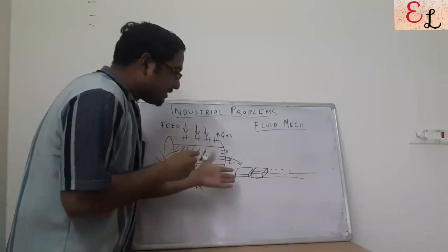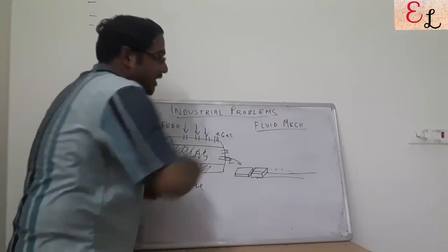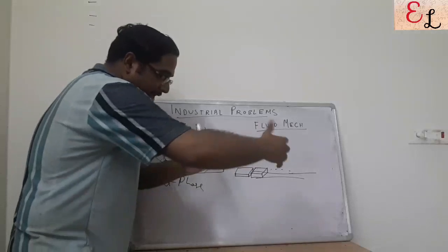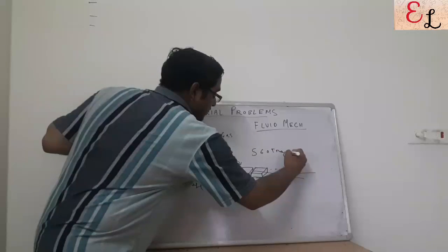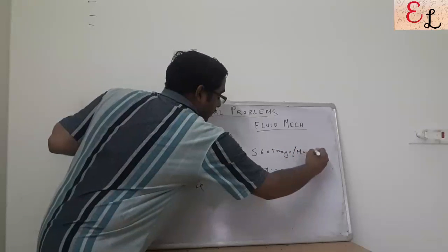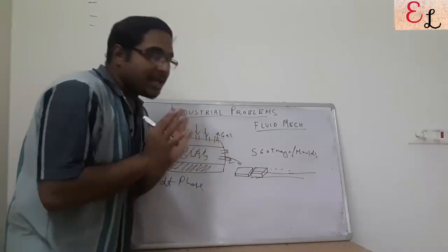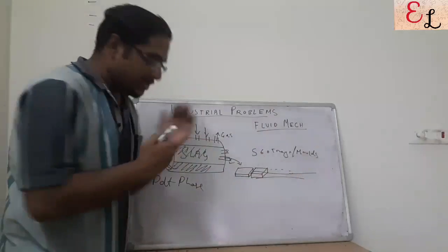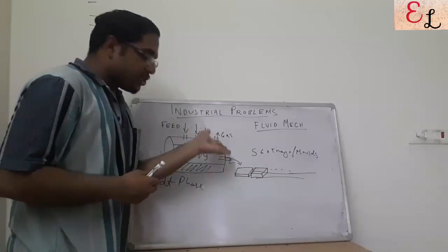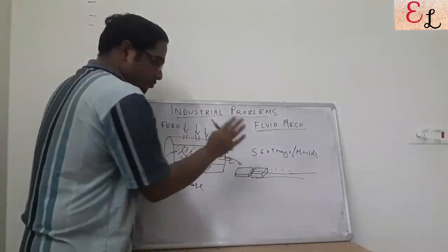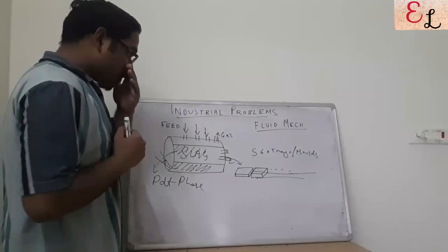There are trays fit in the line. The line is approximately 96 meters in length, and there are approximately 560 trays or molds fitted to the rail, and it's a continuously moving railway line. One mold gets filled up, the next mold gets filled up, and like this the slag keeps on filling in these molds. Once the pressure stops coming from inside, the flow is stopped and the hole is closed temporarily.